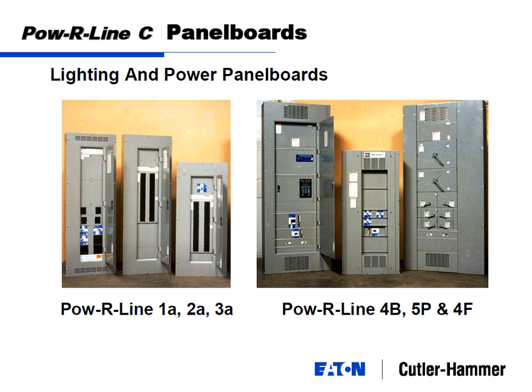So with that said, ground fault is another reason. If you need ground fault protection, circuit breakers provide ground fault protection capabilities. Circuit breakers give you the ability to move that trip curve and coordinate your entire system so things trip in the proper order. Now, what do you suppose we manufacture, circuit breakers or fuses? Space, also, we'll touch on that, but space is another consideration.